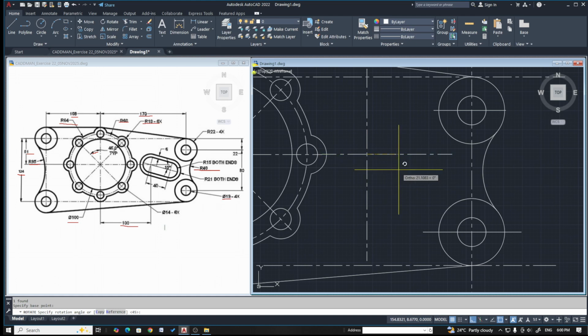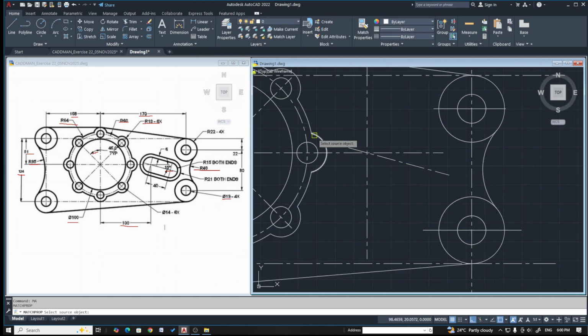Now we wanted to rotate it to 15 degree because the angle parallel to these four lines is given as 15 with the horizontal. So let's try to rotate. We are rotating it clockwise, so the value will be negative. So minus 15. So I'll try to stretch this out. Now let's make this a solid line for a while, and let's try to offset.